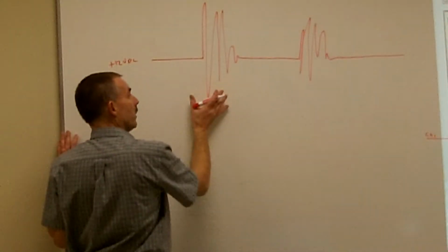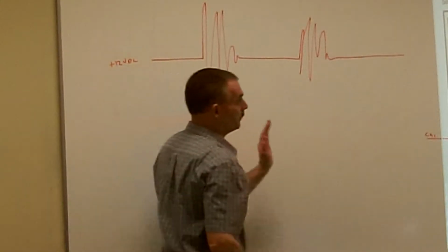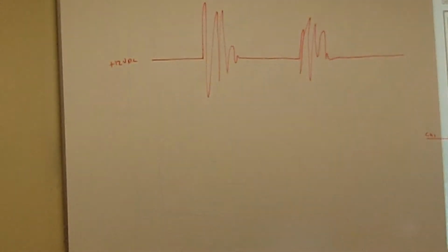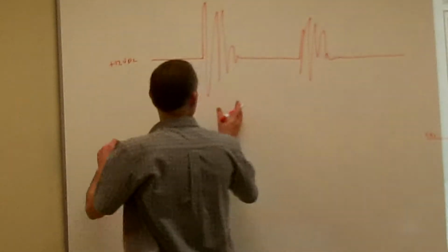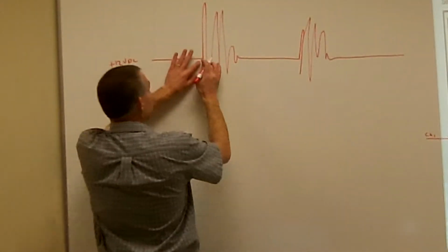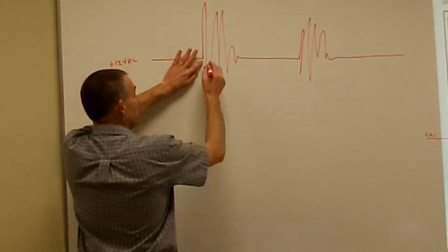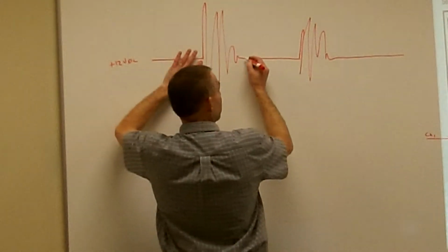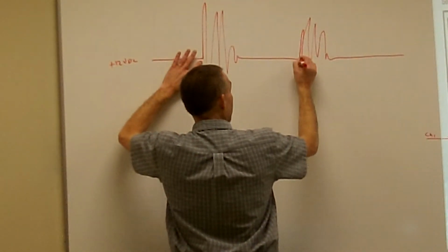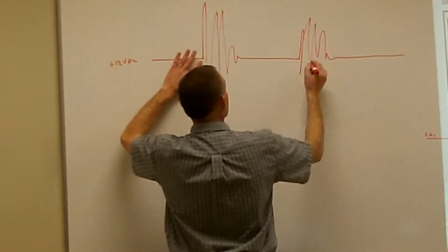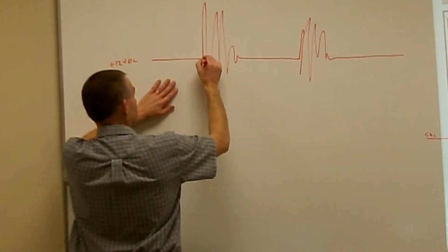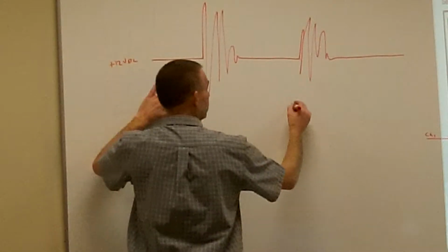So what I'm doing is analyzing the signal. Now when the oscilloscope looks at it, it's trying to figure out what the period is. Here's the beginning of my cycle, it sees this, then it goes, and repeats itself at this point. So what it thinks is the frequency is from here to here.